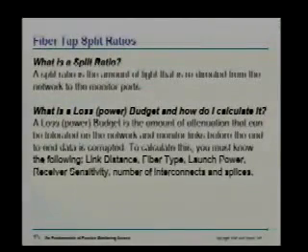Split ratio essentially, like I said, is the amount of light you're willing to tolerate giving up on the network link. The way you generally calculate a split ratio is by looking at your end-to-end distance and coming up with a loss budget or power budget. It's really the attenuation that you have on the link: cabling distance, network distance, patch panel interconnect, splicing.